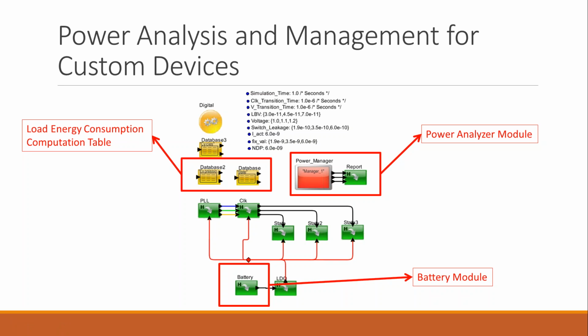Now, power analysis and management for custom devices. One of the key things is a lot of times we provide the device blocks. We have about 100 or so different types of hardware and software devices that we provide. Now, some of those may not be sufficient. Say you have a fully custom one. You can actually create your own states, and then you can define the energy consumption for each of the states.